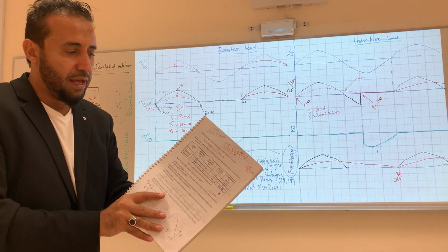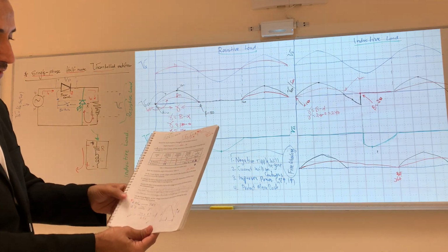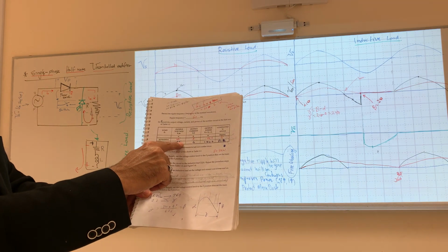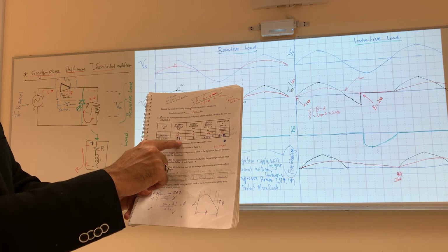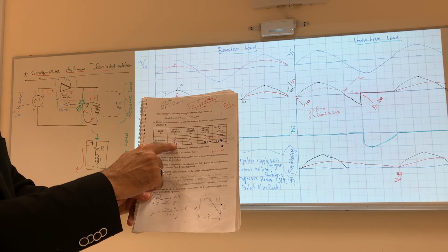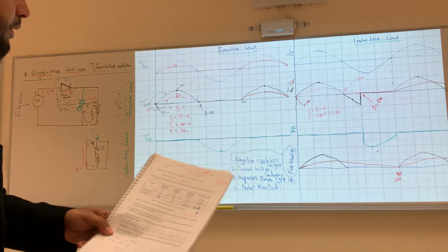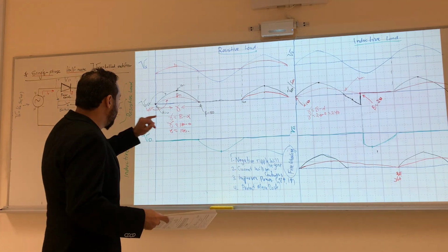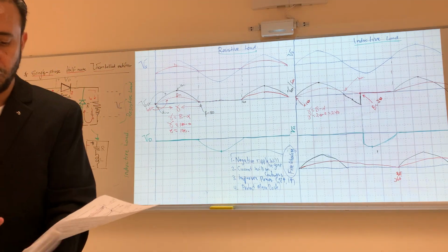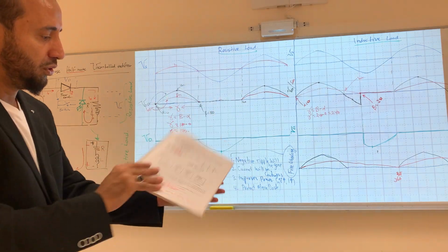So, and then here in this table right here on page 5, you just take the readings. You will notice that the resistive load voltage is higher, and then the inductive voltage is lower. Also the current. See here it was 49, then it goes down with inductive to 38. Current was 0.8, it goes to 0.6, and so on. Okay? The conduction angle is 180, but for the inductive it should be bigger. You should do the calculation, okay? And your drawing will be here, same as those.